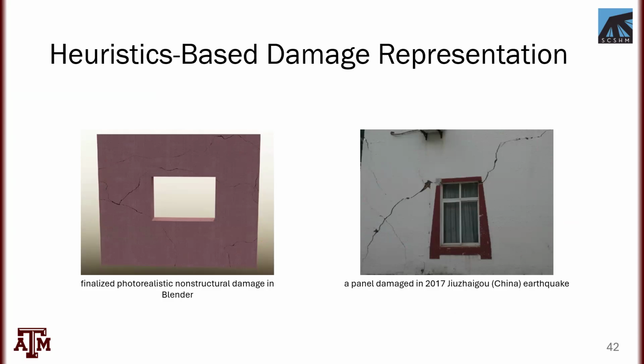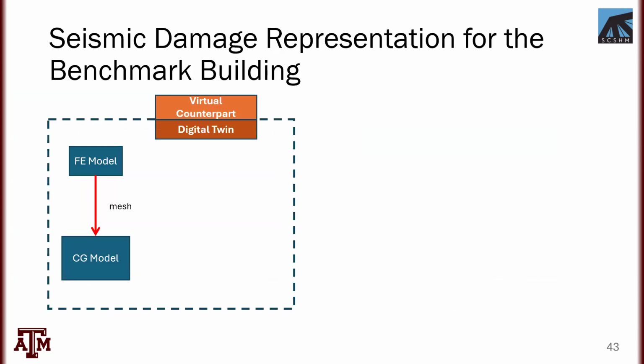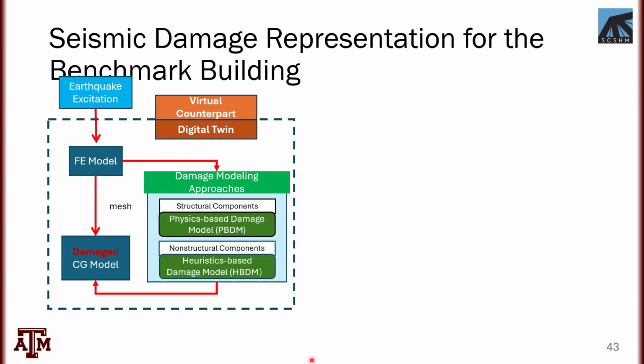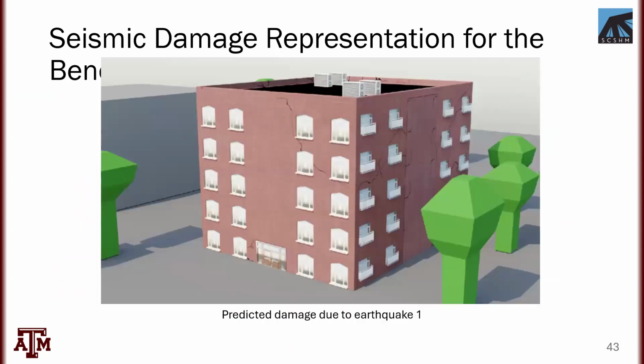And then finally, we put all of this together into a benchmark problem for a seismic application. So again, we have our virtual twin. It has the finite element components. It has the computer graphics model. We give it a whole bunch of earthquakes. Within this environment, we have physics-based simulation. We have heuristic-based simulation. And we can see the response to earthquake 1.